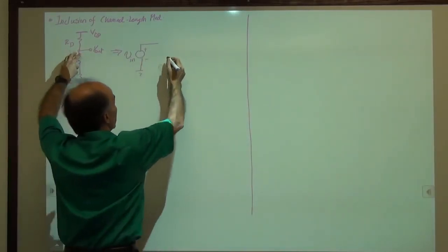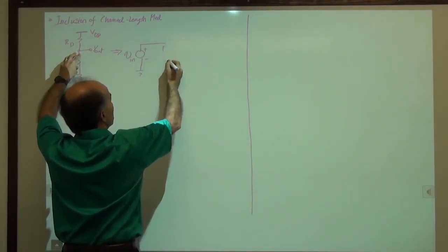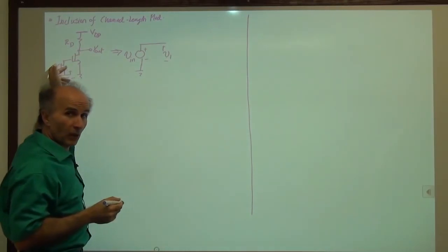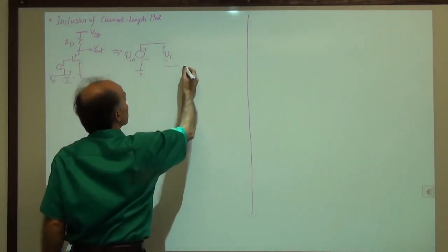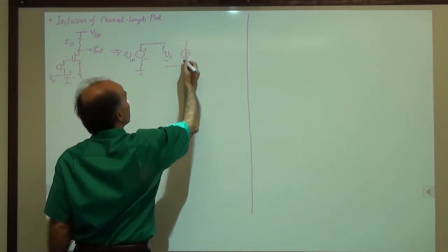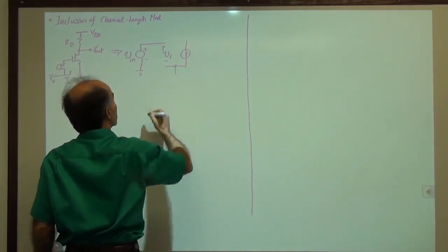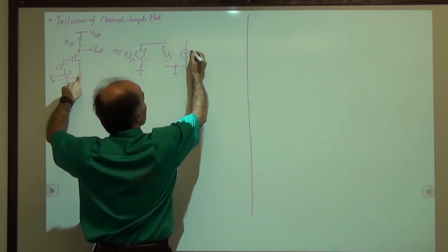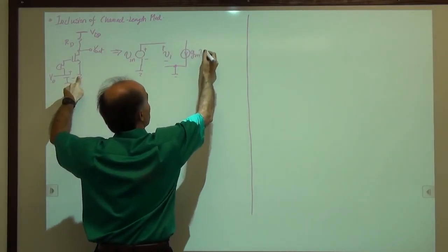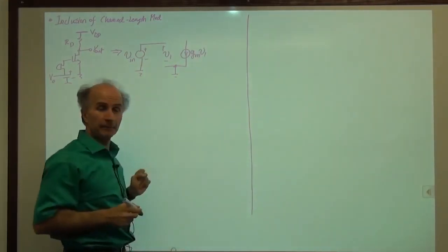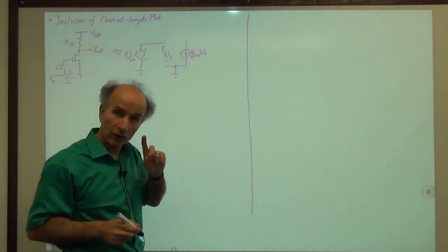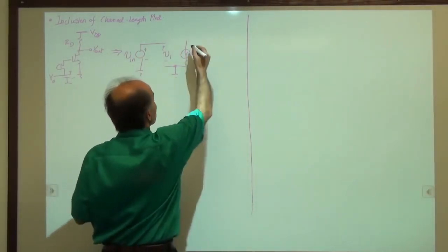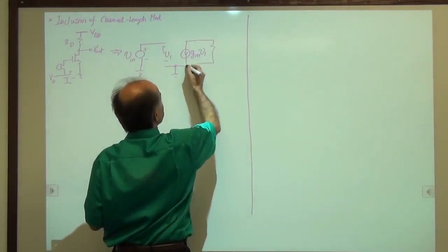For the MOSFET, we have to have a small signal model, assuming, of course, that the signal that's coming in from the microphone is small. And now we have the source. The source goes to ground, so that's good. This voltage-dependent current source is given by GMV1. And then we have to add RO to represent the channel length modulation effect. So we have RO here.